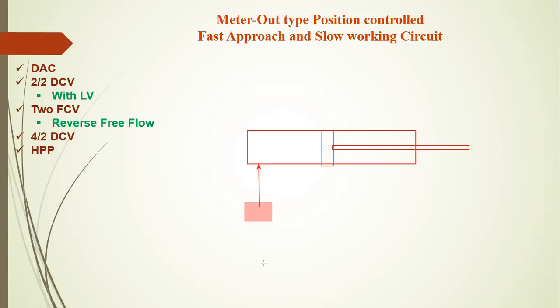This means the oil passes into the double acting cylinder on the first side. If you give the additional attachment at this other point, that is called a meter out circuit. Both are different. If the additional attachment is given at the entry point, or extension working side, it is called a meter in circuit.